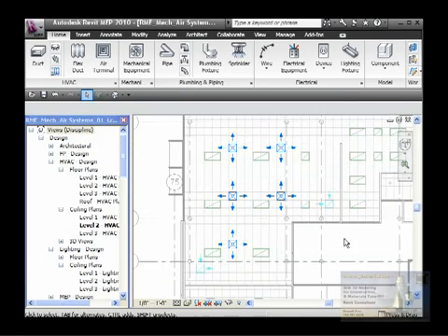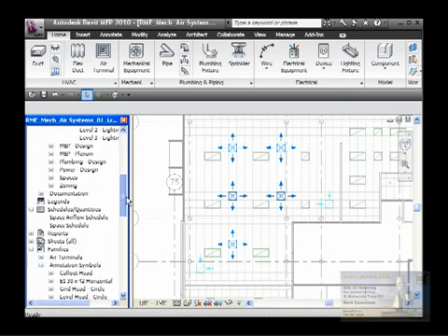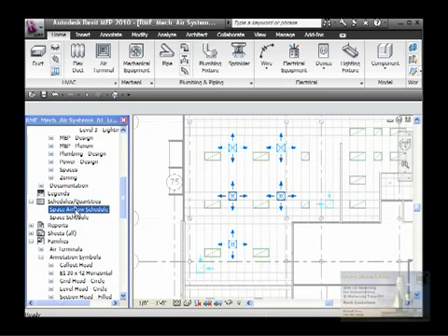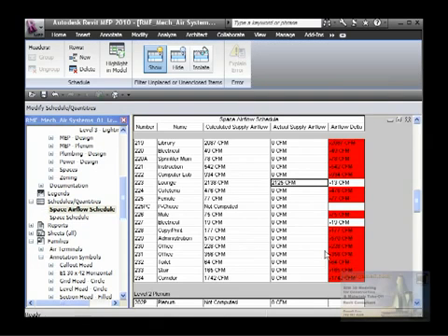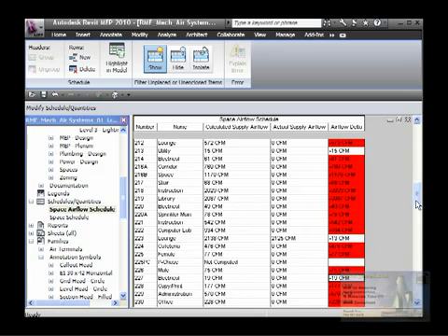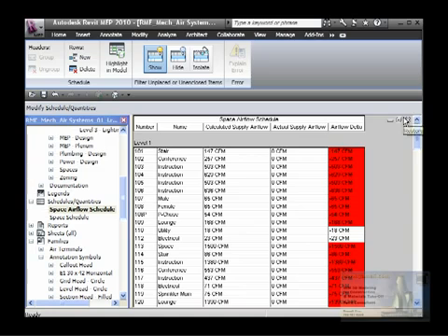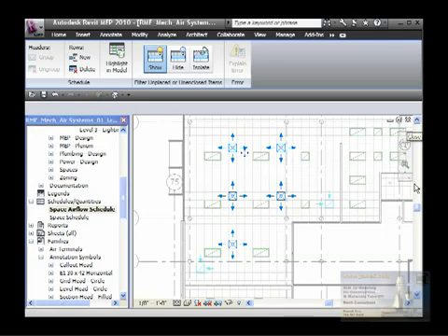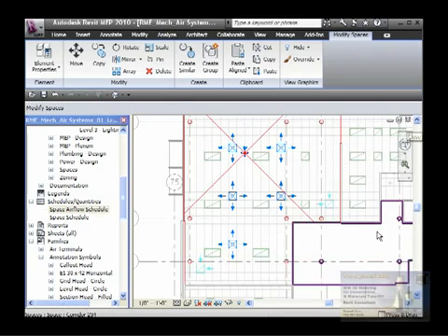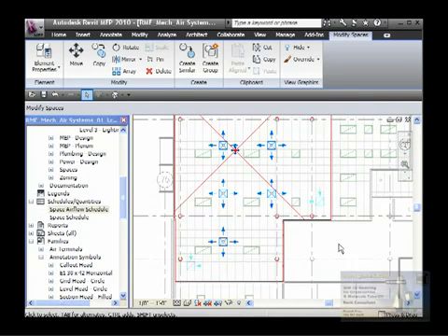So I have return and diffusers, and let's see again the airflow schedule. And this is a different room, but like I said, because the requested airflow was only 19, it is within the range, that's why it's not red. But in reality I haven't put anything to that one. But I did put to this one. Okay, so nothing has changed obviously because right here is not including anything of the returns. So let's close this. We don't need to keep looking. This is doing the job, and when we work in another room we use it to make sure we have enough diffusers.